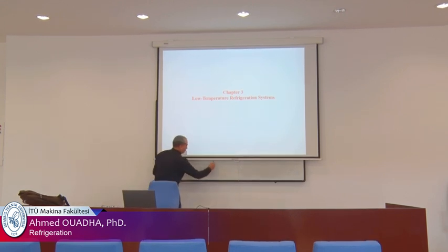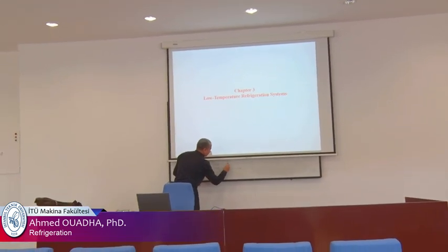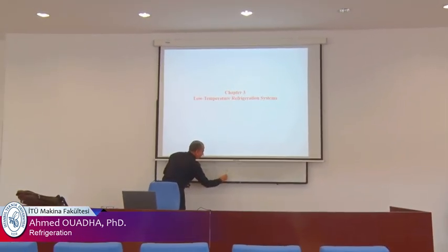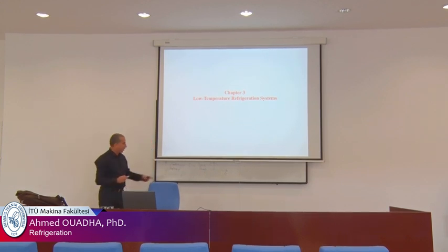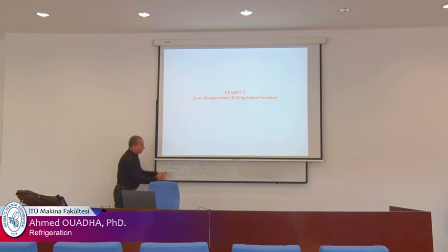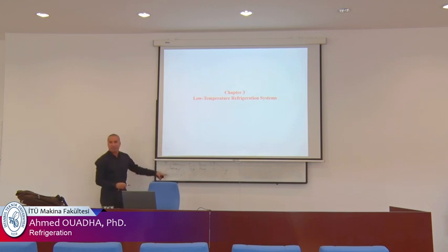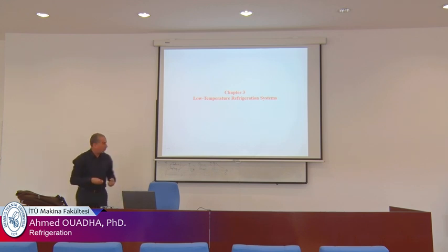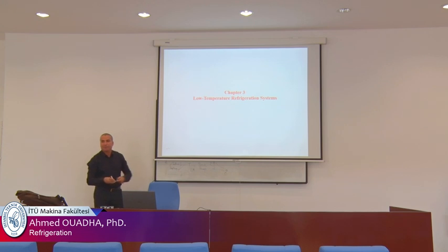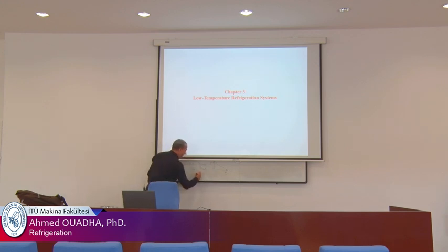It means the efficiency of the compressor varies like this with the pressure ratio of the compressor. What does it mean that tau increases here in the cycle? You follow with me? What does it mean when tau increases? It means that P condensation increases or P evaporation decreases.